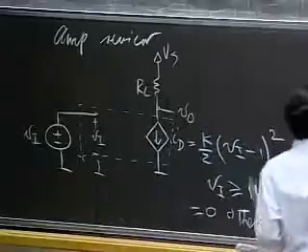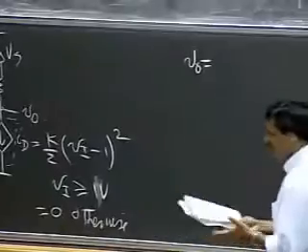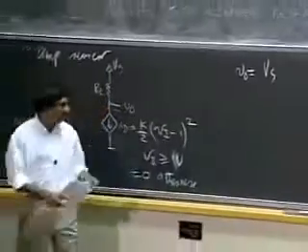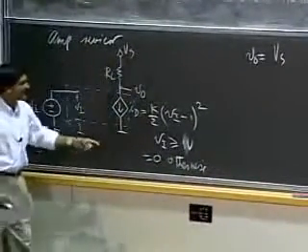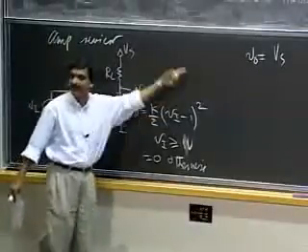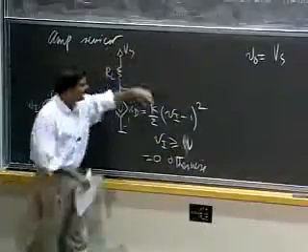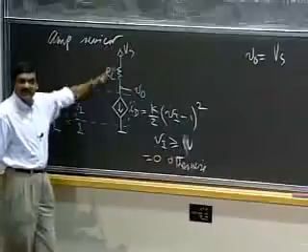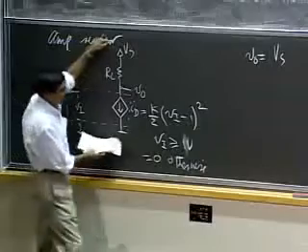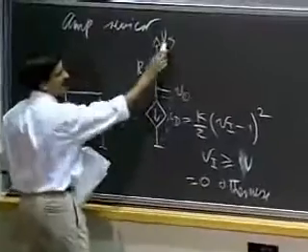So we can analyze the circuit to figure out what VO is going to look like. A simple application of KVL at this loop here. Again, when I say this loop here, I'm pointing at something here. That is the VS source that is implicitly across these two nodes. Again, this is a shorthand notation where this little up arrow implies that I have a voltage source connected between these two terminals here.